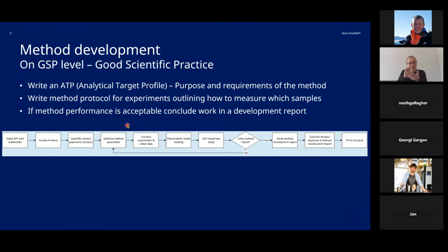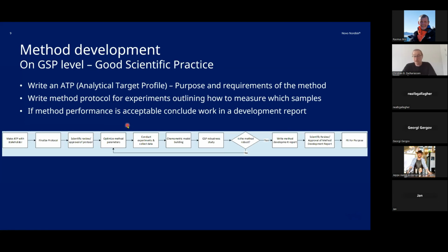And then you need to log when you took the background, and then for every measurement, which background I used. And then you need a reviewer to check that the human who took the measurement did not use an invalid background. So if the software does not help us enforce GMP rules, we will have to add human reviewers to exclude the chance of taking a measurement with an expired background.